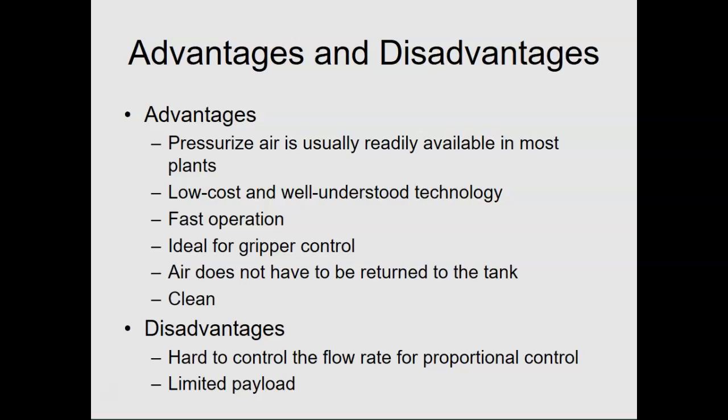So low cost and well understood technology backs this up. It's very fast operation. We use this very frequently for grippers and other tools. Air does not have to be returned to tank. It can be vented back to the air. And it is a very clean technology. However, controlling the flow rate for proportional control can be a pain. And if you over pressurize air, it actually can turn into a liquid in your pipes, thus causing other problems. So it's got its advantages, but it's got its downsides too.